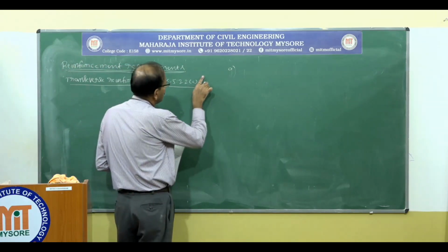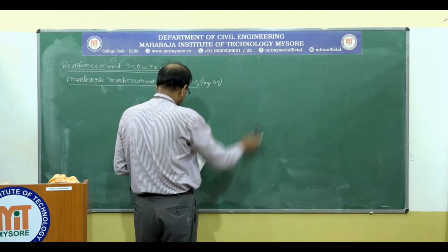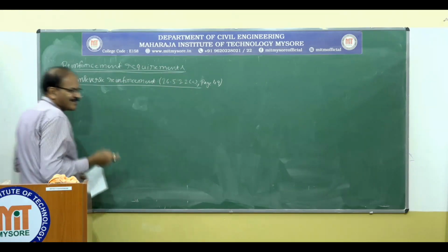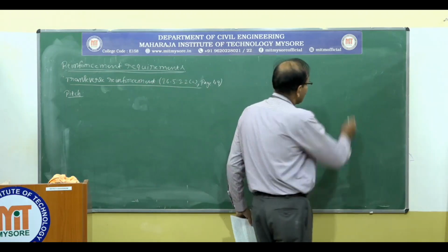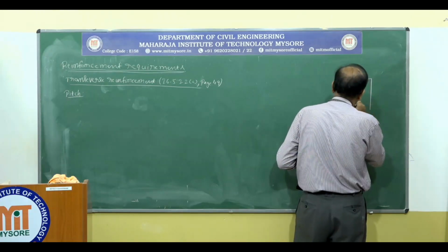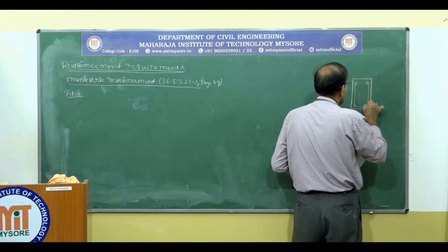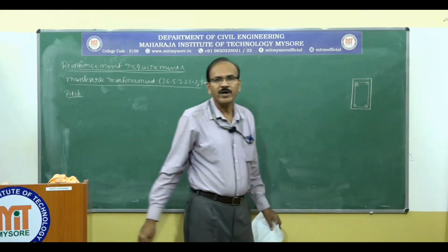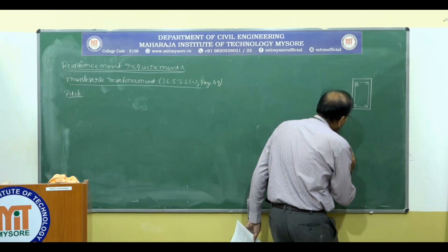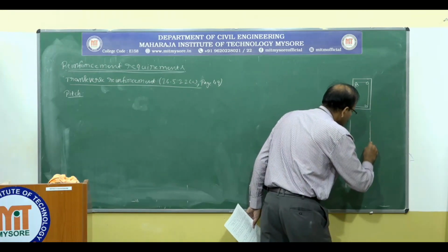So that is again page 49. So pitch. So that is the spacing of the transverse reinforcement. Again, if I take a column like this, rectangular one, so if I look at the plan, I see like this. So this is the transverse reinforcement, and if I look at this in the elevation, I am going to see this.